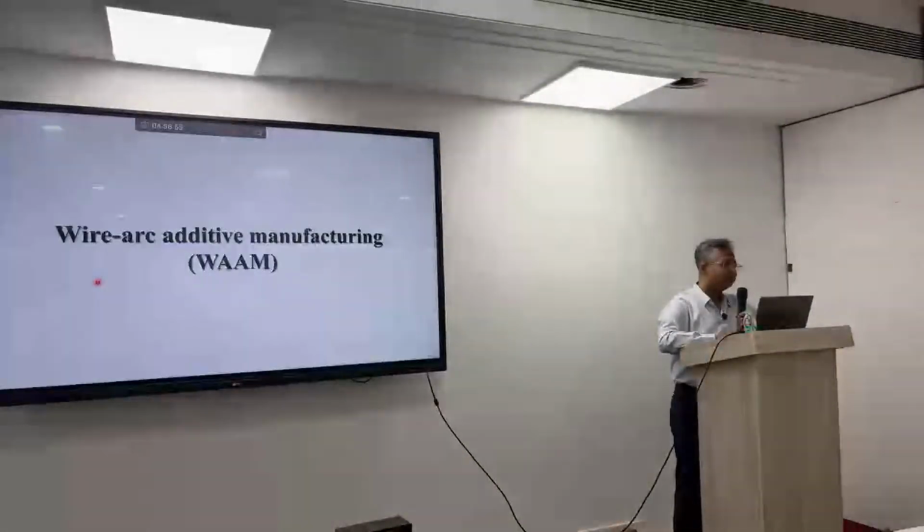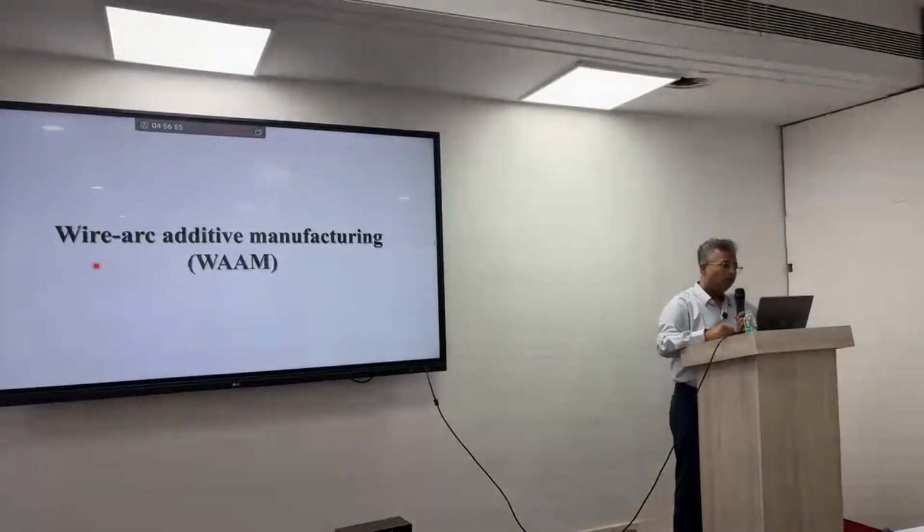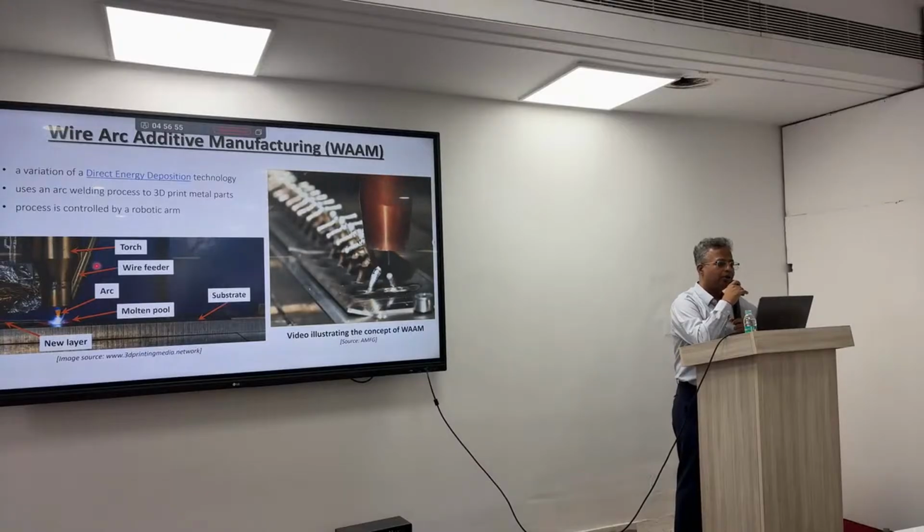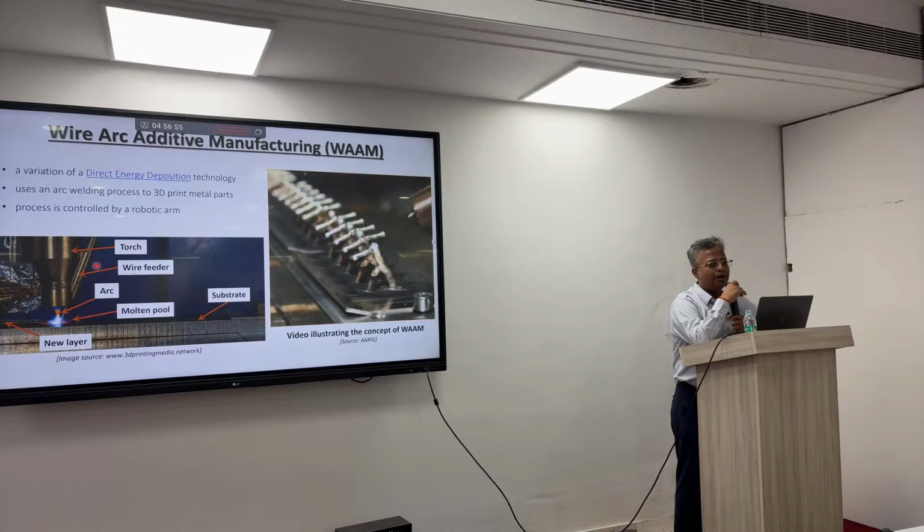Okay, then we can utilize the welding process also, which is known as wire arc additive manufacturing, to do additive manufacturing. There is a video once again, you can just have a look at this video. This shows us how the cold metal transfer, CMT process, or MIG, metal inert gas welding process, can be used to deposit the material and make the component.